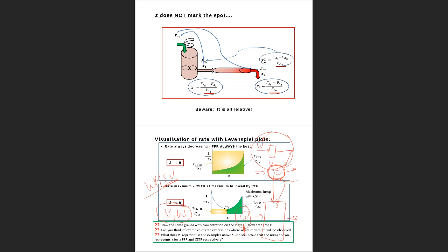It's a scalable factor. Yes, you were all correct in that it says how long the material must stay in there. But for a specific reactor type, if you just have lab scale measurements, it's easy. When I evaluate the design projects at the end of the year, I look at the kinetics and I look at the kinds of reactors that were sized in the papers where they published the reaction kinetics.